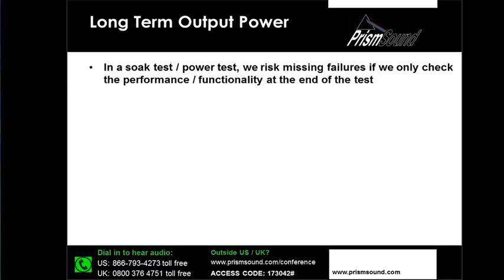But more than that, we also want to know whether the amplifier worked flawlessly throughout the test, or whether perhaps some form of thermal protection may have engaged mid-test. So this helps us to determine whether the amplifier has been designed correctly, so we've got the heatsink calculations correct if we've determined that a heatsink is needed, and it tells us whether the thing has been built correctly and the output devices have been thermally coupled to their heatsinks correctly if heatsinks are present. So this is a reliability test, which is rather different to just a continuous output power test.